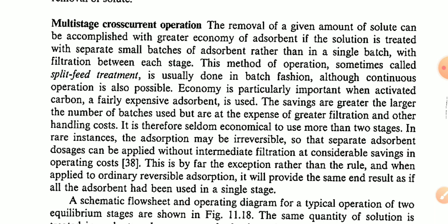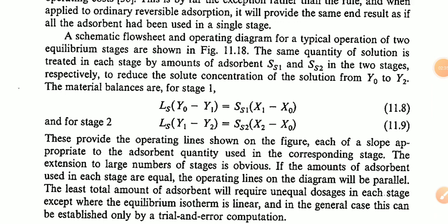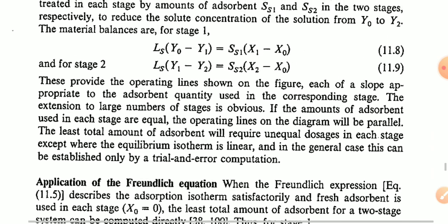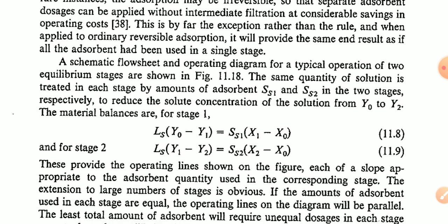Now, a simple schematic flow sheet and operating diagram of a typical operation of two equilibrium stages is shown in Figure 11.18. The same quantity of solution is treated in each stage by amounts of adsorbent SS1 and SS2 in the two stages respectively,